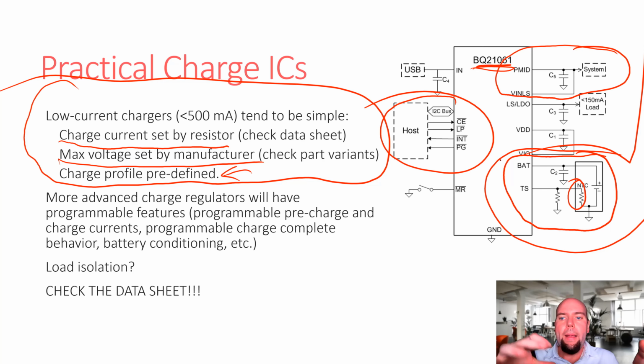So you want to be able to pluck the battery out of the circuit and charge it, because when you do that, you know that any current I send to the battery is actually going to charge the battery. I know what I'm doing to this battery. If a load is connected to it, as the battery charge controller, you don't know how much current the load is drawing. You don't really know what you're doing.